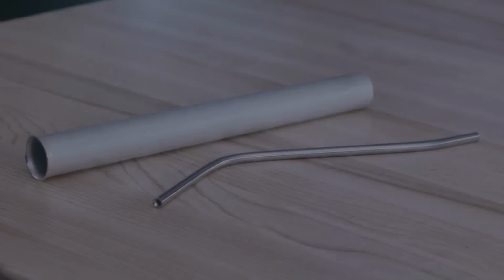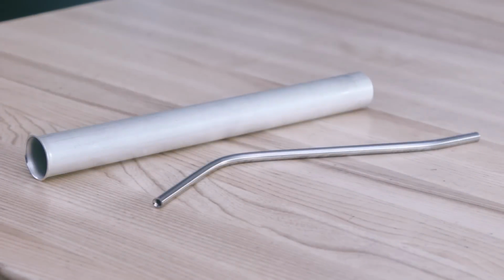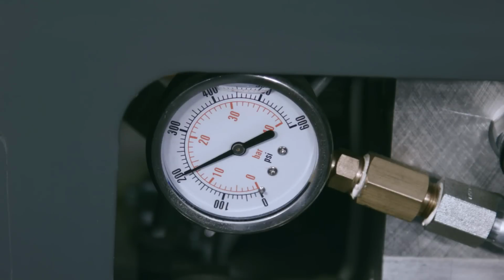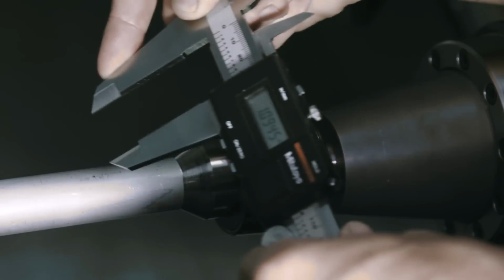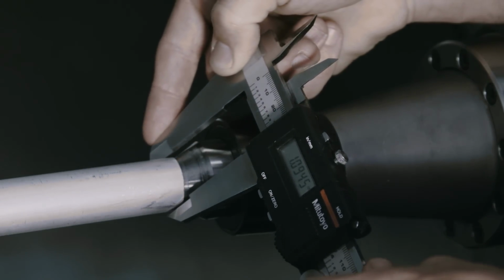Okay, so why did we show you this? We want you to realize that 200 psi will probably not work for some weaker parts. The point is, when your part is fragile, take some measurements to find where it starts to deform and keep your tailstock pressure below this point.